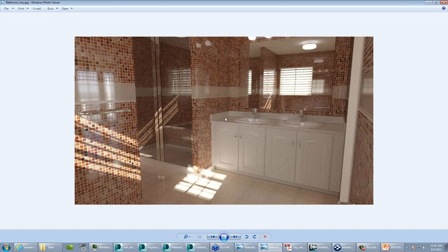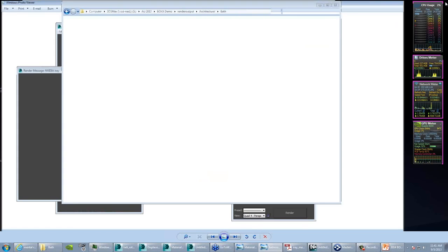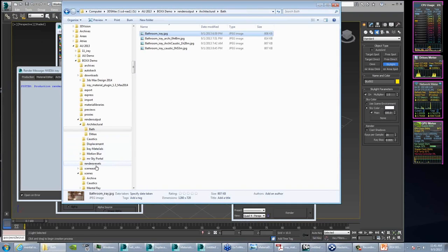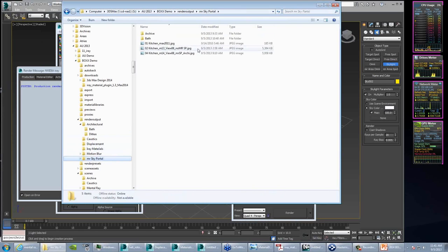Mental ray sky portals are supported by Iray. There's not a lot of additional overhead that's generated by adding those, and it's really only a clue to the renderer that there's a portal to the outside. And it's really only necessary on rather small portals. So in this scene here, in my tests, adding a mental ray sky portal didn't add anything to the illumination of the scene. So a much smaller opening would make a difference in that case.